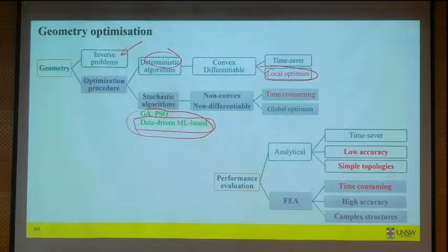In your first generation, you could have hundreds of designs, and finite element needs to analyze hundreds of these designs to calculate flux density, torque, and efficiency, compare them, and then tell you, okay, this is the best design. So that takes time, and that's why FE-based evaluation is time consuming.